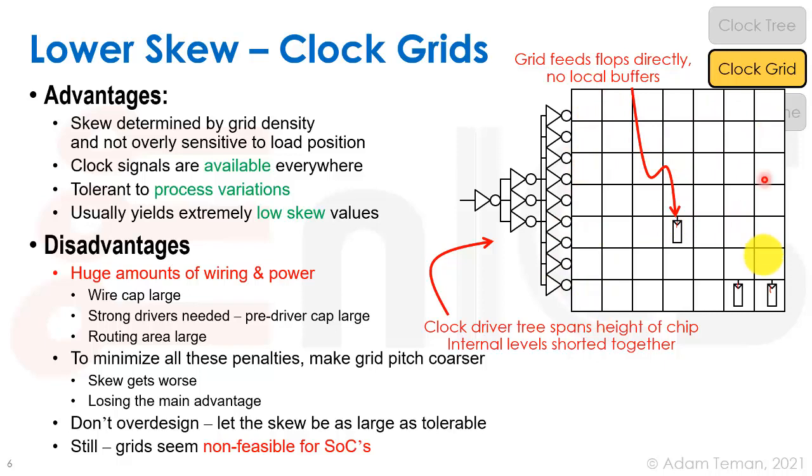They probably will even take up pretty much a whole metal layer, maybe 2 if we have something like that. And this is going to be a huge wire with huge capacitance, and therefore we're going to need a real big driver to drive it. Not only that, we're going to want to distribute the driver such that it doesn't touch here like in this two-dimensional picture, but actually each of these final stage buffers are at a different little point across the grid. So we actually have really the same skew, the same time. We have an equipotential at every single point spatially in our design.